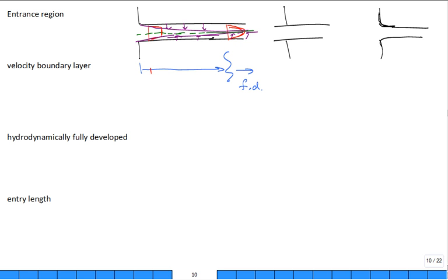When I do the cross section, I just have the top and the bottom. But for a round pipe, you have right side, left side, top, bottom. It's just growing from the walls toward the center line. So we think of the growth of a boundary layer, and it's thicker as you go. Let me try and draw it like this until it gets out to R. And then when it gets to R, close enough to R, it's fully developed.